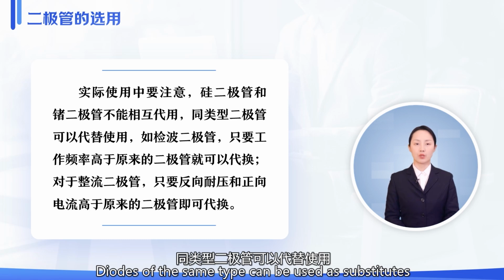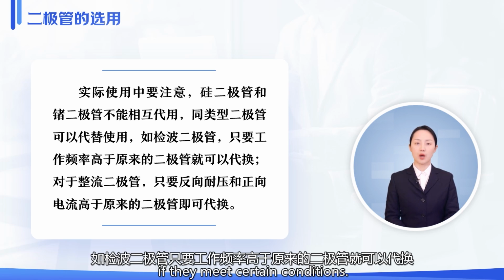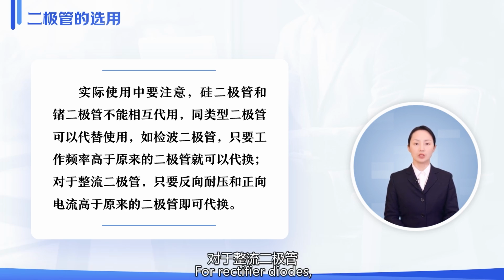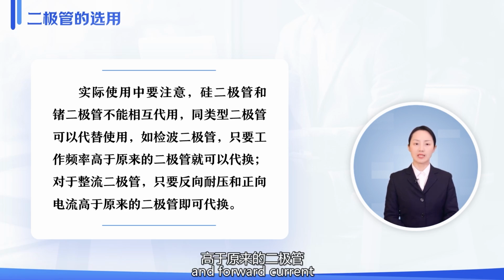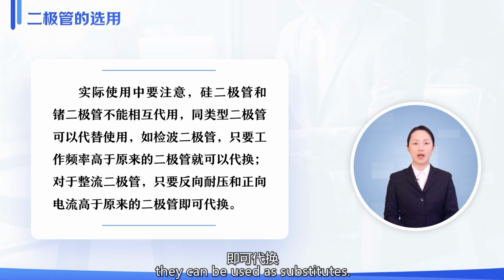Diodes of the same type can be used as substitutes. If they meet certain conditions for rectifier diodes, as long as the reverse voltage withstand and forward current are higher than those of the original diodes, they can be used as substitutes.